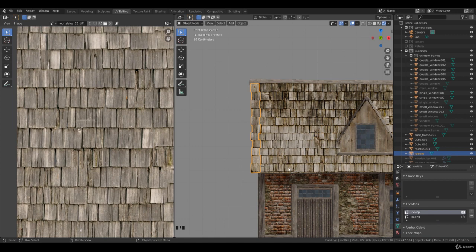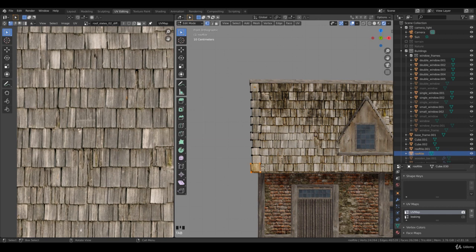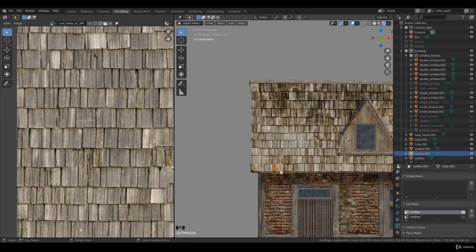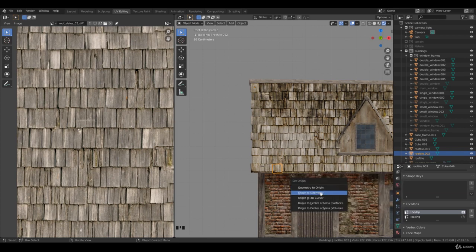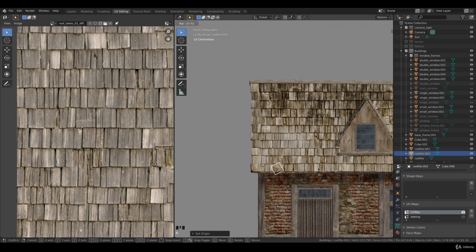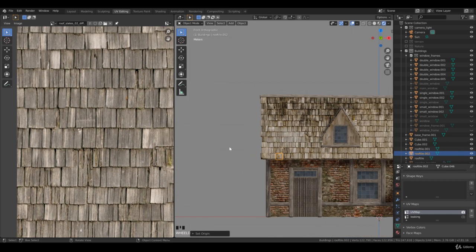Before you can do this yourself, you can see this is a joint mesh. You just grab one, so left click on one and Shift D, and you want to make a single roof tile, and we had to do this before, we didn't do that. Press P, make a selection. So, and press spacebar. You want to make it origin and set origin to geometry. So now the center is on this roof tile, and it says it's a single mesh. Good, I will pause the video, and good luck with the roof tiles on the bottom.